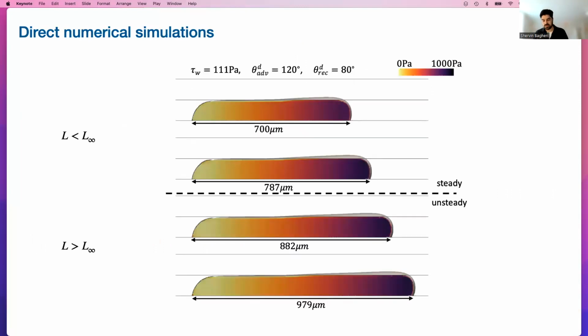And we did this. We created these finite cavities, and we could retain pretty much all the lubricant for partially wetting surfaces. So it's a little bit counterintuitive: you create a surface that dislikes the lubricant, but you can actually retain the lubricant there because there's a contact line hysteresis.